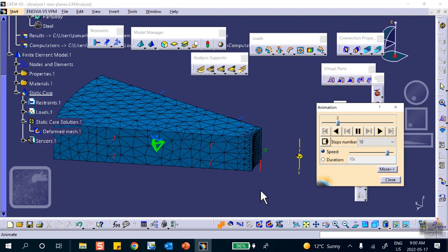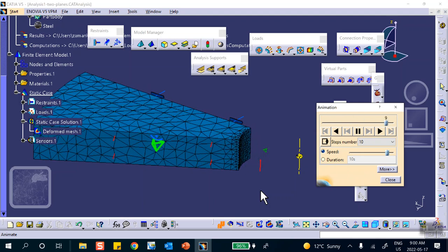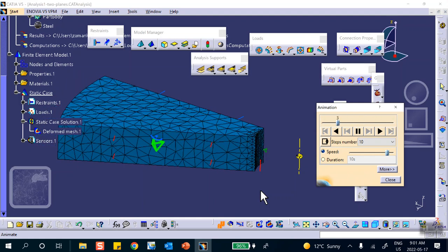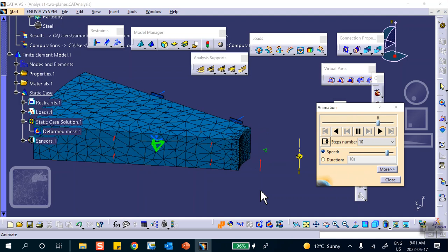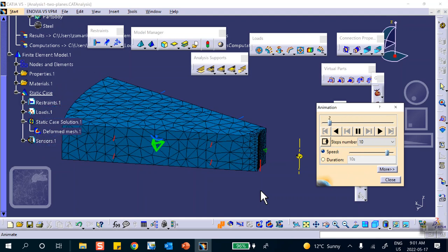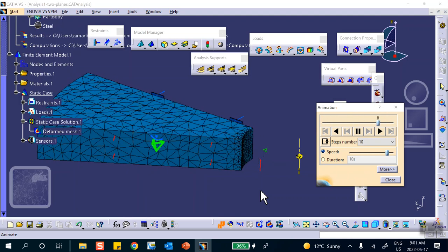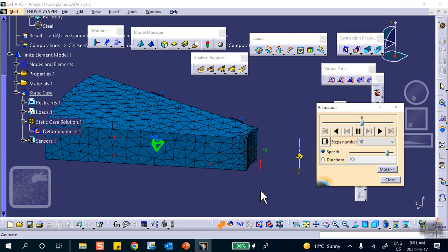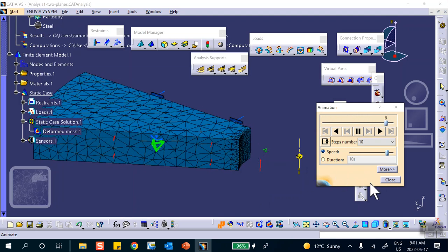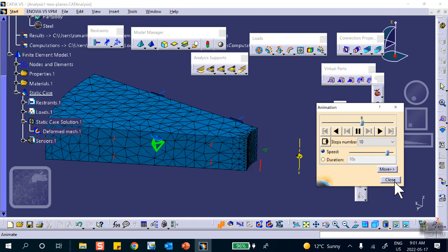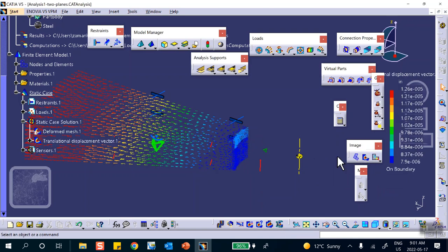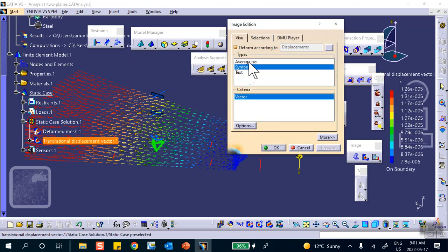Okay? Now, it is not quite clear here. We've got to look at it more carefully. It looks like what it's supposed to. This disk is rotating. It visibly goes out. It looks like that, but there's something that's bothering me right now. I'm not sure. Let's look at the contours of displacement, for example. They better be rings. They all go the same way. They better be rings. This is kind of tilting. I don't like that. We'll find out what's going on. Okay, so maybe not.